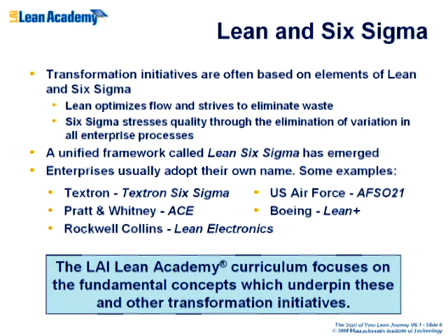I just came from Boeing helicopters. I was there for a week last week, helping them on the root end fatigue problem on the Apache attack helicopter advanced composite rotor blade program. And there's a root end problem, and I was there to fix it. But we literally take 6 specimens, which has nothing to do with Six Sigma per se, and then run out the fatigue test and determine what the high confidence, 99.999% stress level is that we can guarantee the life of the part. And so it's used a lot.